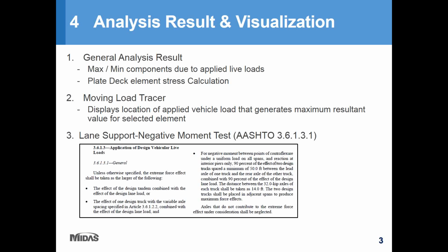We also have something called lane support negative moment test. We call it the dual truck test. Our program has a function to apply this AASHTO 3.6.1.3.1. And I will demonstrate this modifier shortly after all the slides.